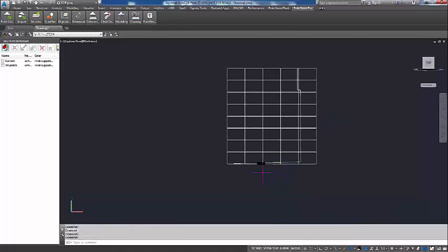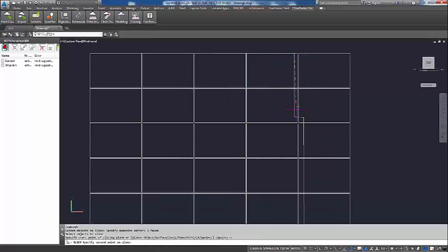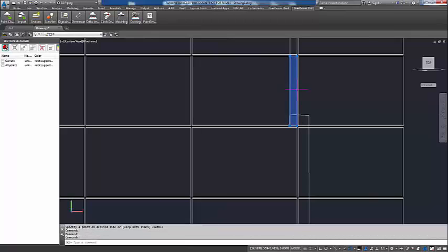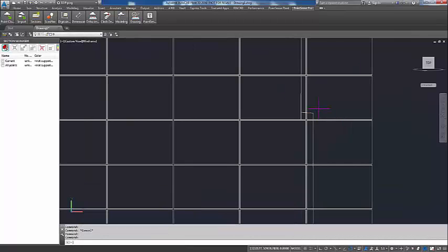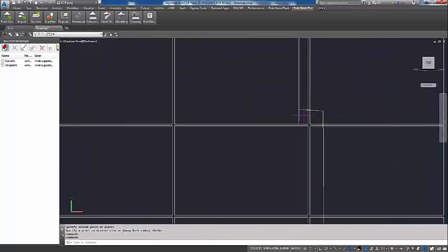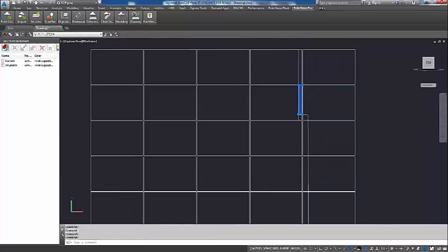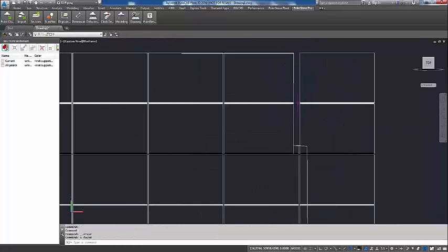and we can then start slicing, just using the AutoCAD slice now to specify the extents of the panel here. So I slice there, and it creates this 3D slice where I can chop off a portion of the panel. And just keep repeating slice. And then we can remove this portion that's inside of the wall.